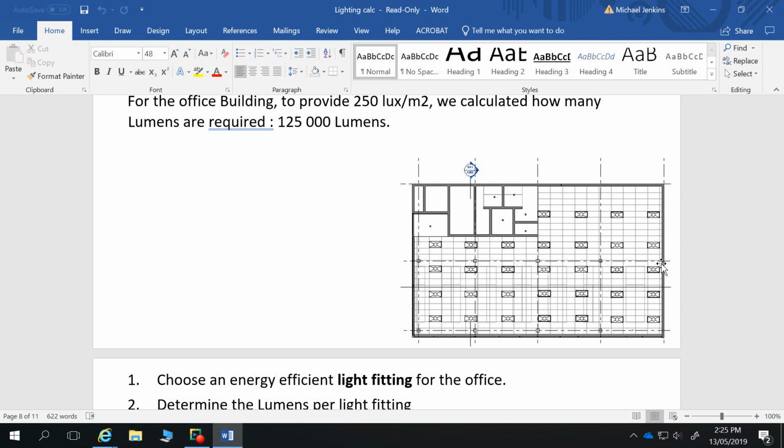When you're producing a reflected ceiling plan, that reflected ceiling plan is the same as your floor plan, but it's as if you're just dropping lights directly on there. Now, if you were to lie on the floor and look at the ceiling plan, it would actually be the opposite of that. But to make our reflected ceiling plan relevant or easily compared to our floor plan, we do it from up above, but as if we were looking at the lights. That makes sense. So it's like there was mirrors all on the floor, and you're looking at that ceiling. So that's the way we produce it.